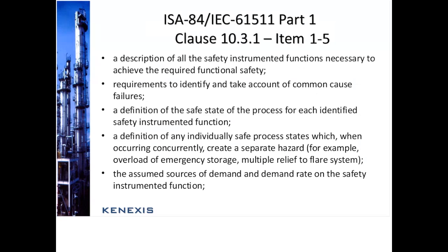Requirements to identify and take account of common cause failures. This is the scenario where maybe two transmitters are on the same tap and that tap gets plugged. We can have a common cause failure of those transmitters, a single point of failure.